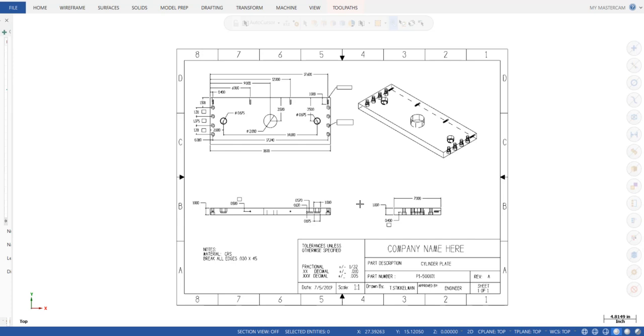So when you're in the shop, go ahead and study the prints and look for those features and look for the information that we just went over, and in your mind process that part, see how many processes it would take to machine that at a minimum, and where you would place your origin based on the dimensioning scheme.